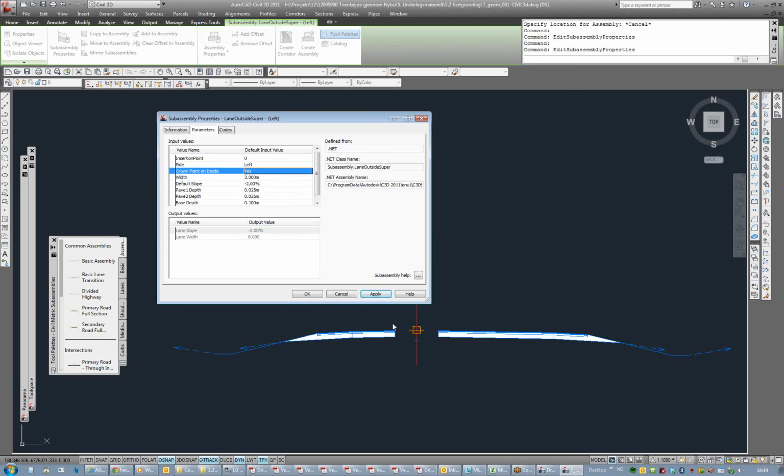Going to crown here. Yeah. We want it to crown here, though. We have to go back this way, don't we? Well, change your slope to 2%. Yeah. Now click apply. Bip. See it jumped so it's crowning here. Yeah. And then you set your pavement section and all that. Whatever you need.